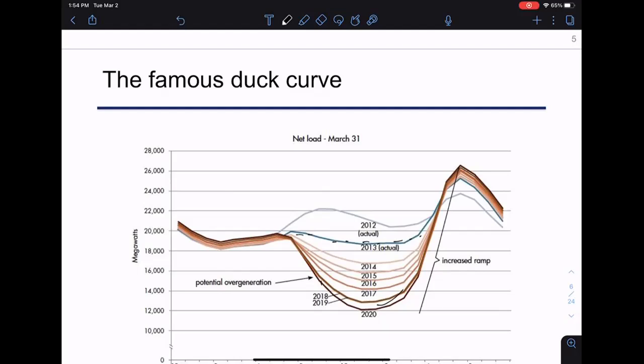So this is a net load plot. This is the load minus solar. Because we have more solar during the day, you have this sort of huge sharp dip in the middle of the day. And this creates problems because this creates huge ramps that we see in our system. Okay, we see huge ramps, right?